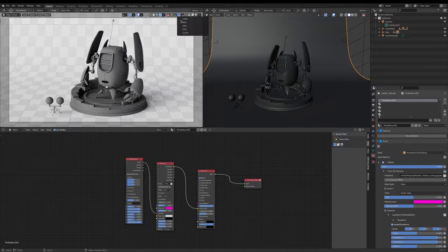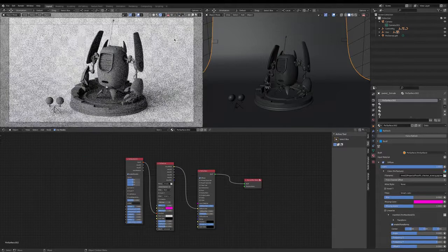This one here allows you to scale the resolution. So you can knock it down to 50% or 33%. And again, it'll render faster. You'll get a much poorer result. This is probably quite useful for heavier scenes where you're trying to adjust the lighting overall, and then you want a faster interaction. So you would knock this percentage down to something like 33. And then when you're happy with it, you can bring it back up to 100%.